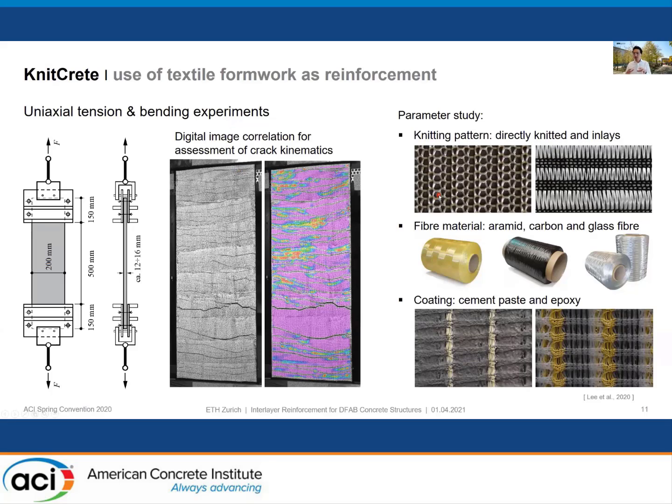This is then like textile reinforcement, but with some particularities, because we are not applying the coating in an industrial environment, and also in these structures, as you saw in the previous slides, we have the textile and only coating and concrete on one side. So we have some particularities, but the behavior is quite similar to textile reinforced concrete.